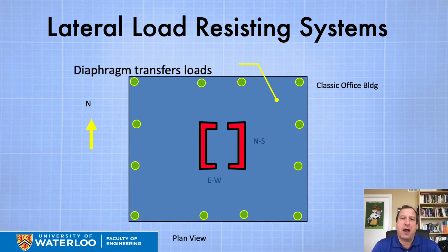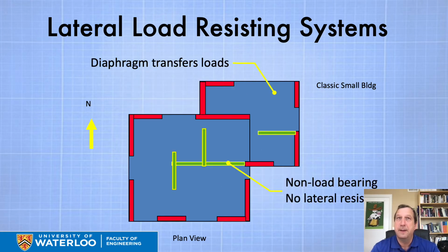And so for low-rise office buildings, the classic system was a central core to provide the lateral resisting, and then the columns at the perimeter all took gravity loads, and then a diaphragm of the floor slab delivered wind and seismic loads to the red drawn core. We can get much more complicated, but recognize that that complication, while it takes a little bit extra effort to calculate, could take a lot extra effort to build, and that's where the money comes in.